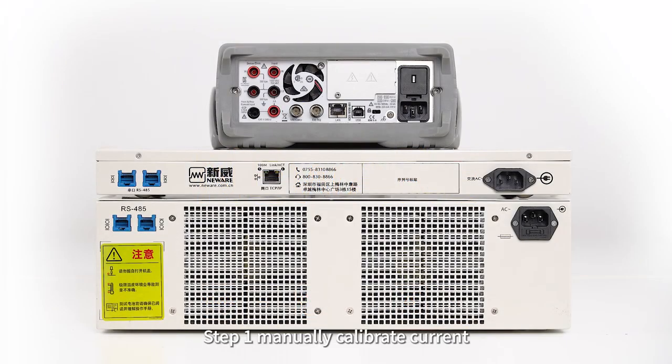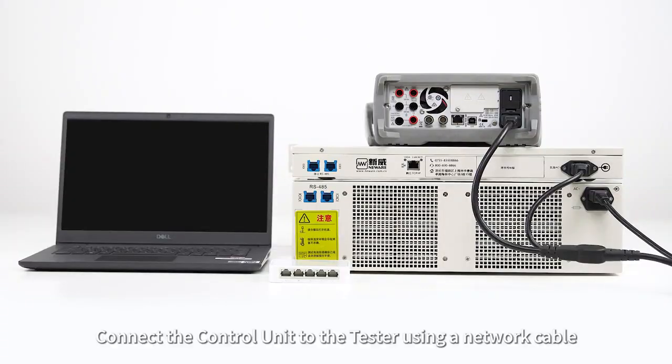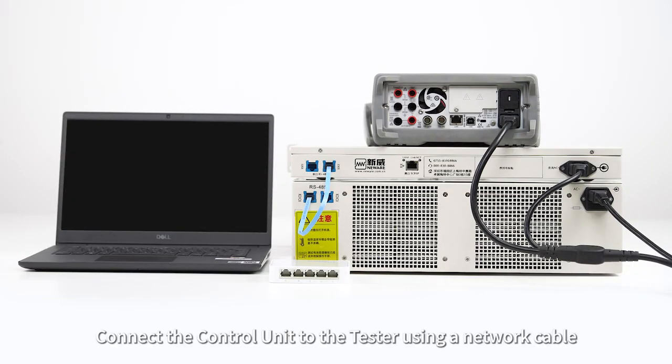Step 1. Manually calibrate current. First, connect the power cables of the multimeter, control unit, and tester. Then there's the cable connection. Connect the control unit to the tester using a network cable.